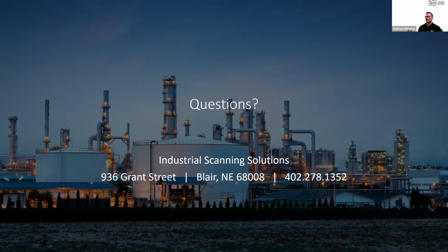The fact that oftentimes we can capture it from outside the fence, but if they want some details inside, we can get in and through all those structures inside and detail that out. So it's a very valuable one. I know traditional survey tools, whether it's GPS or others, can oftentimes have a little bit of difficulty functioning in that environment with the high voltage and the interference that they can have. And also, I personally wouldn't enjoy getting up close and personal with some of that equipment. So it is something that is a big opportunity for 3D scanning to really push in the long run.